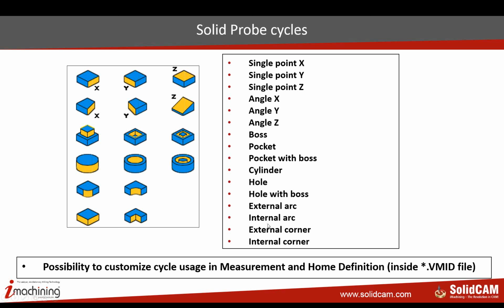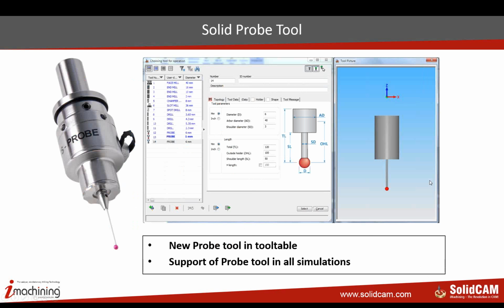But the user interface will include all options. For this we need to define a new tool. We call it SolidProbe tool in the tool table. With a right click you can add the SolidProbe tool today, and it's supported in all simulations.